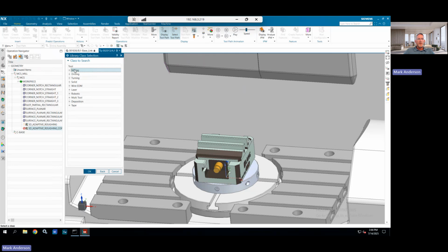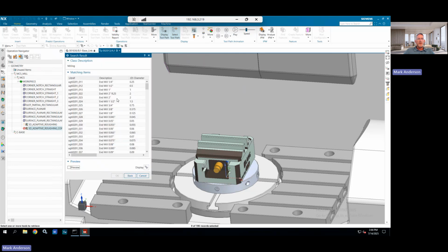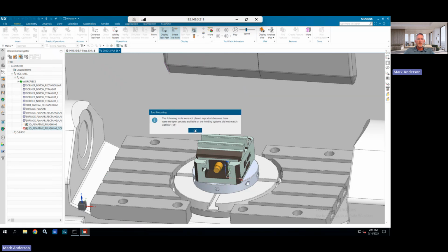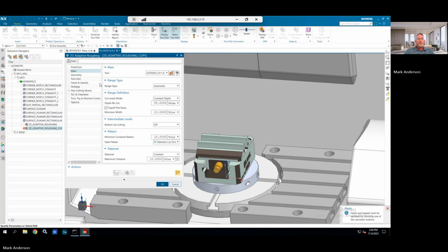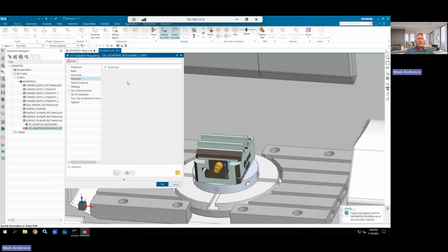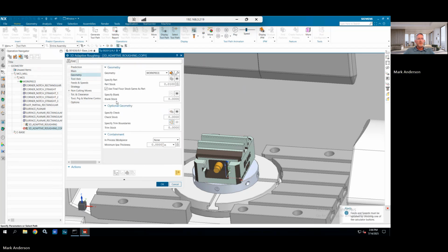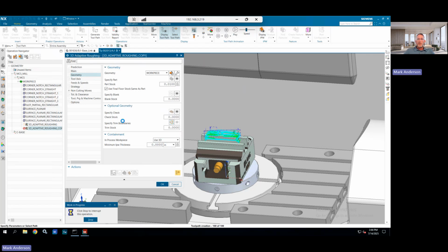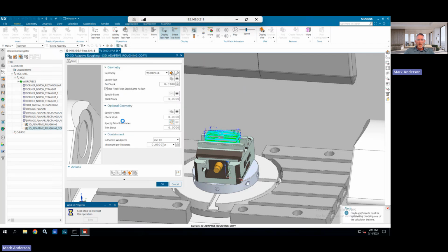This is all coming from libraries, what the feature-based manufacturing system is built upon. Making sure that my 3D IPW is turned on and just regenerating. I'm not having to go out there in active space and touch the part, select surfaces, do anything like that.